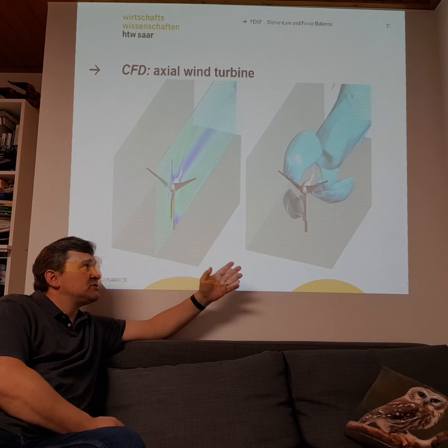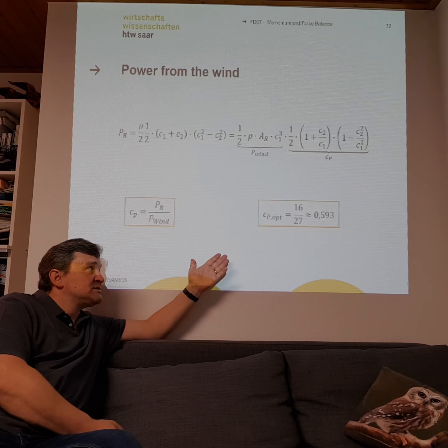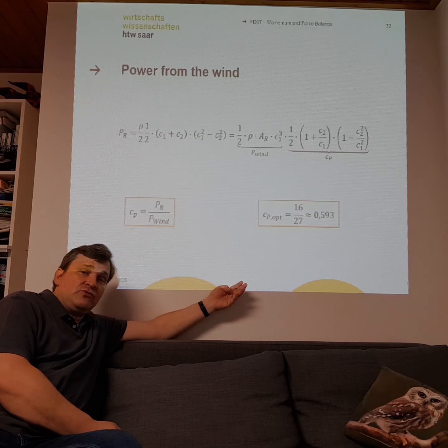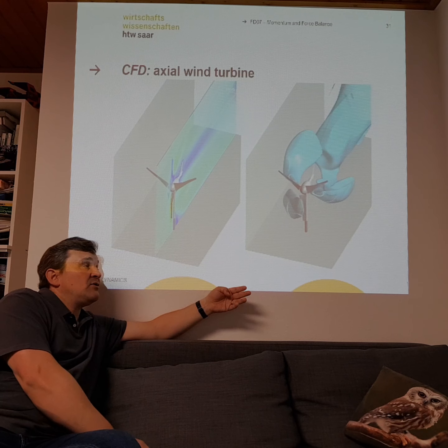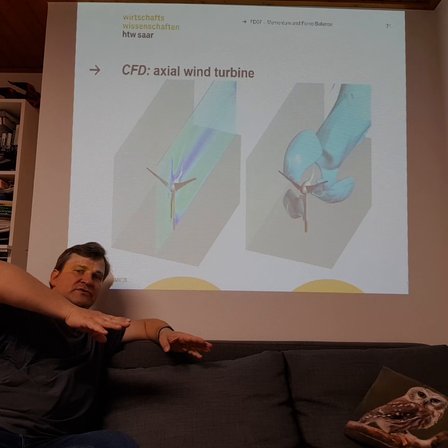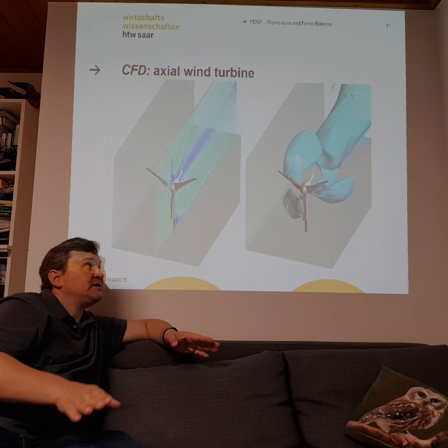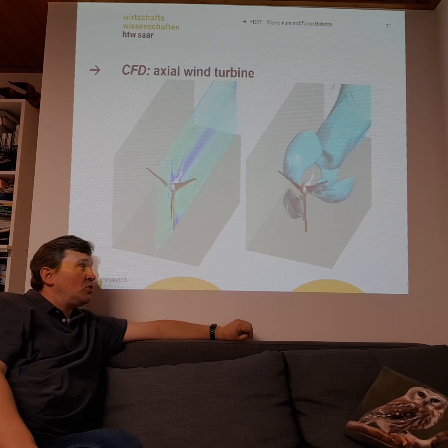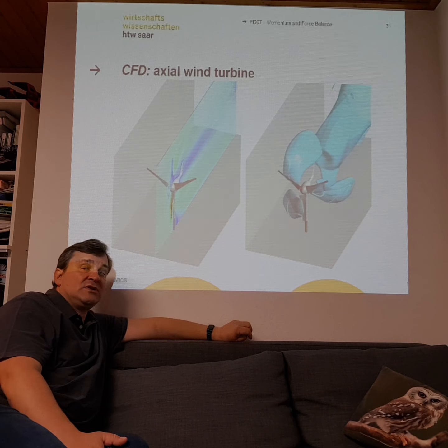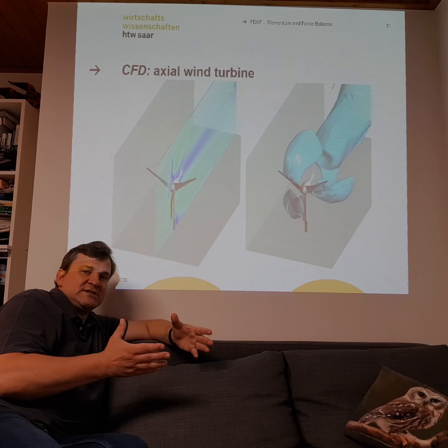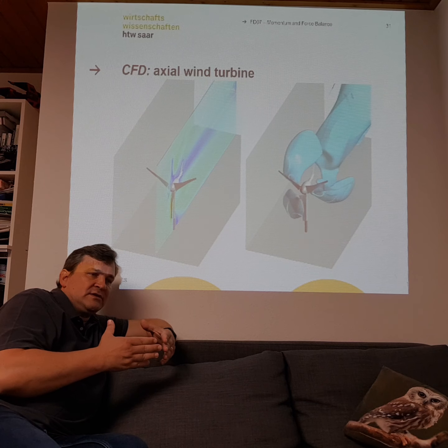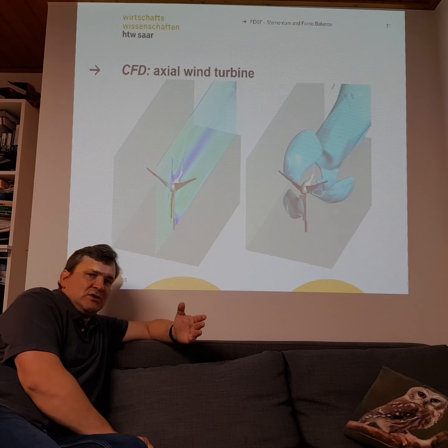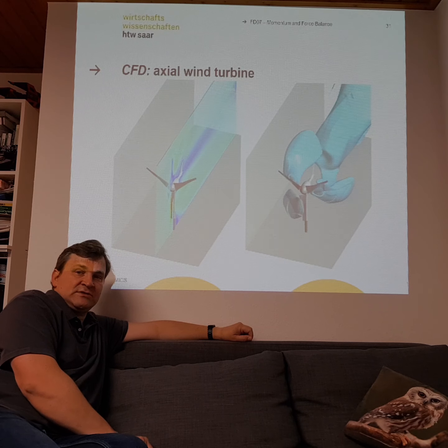Okay, sounds a bit complicated, but you can imagine this maximum efficiency will never really be true, because our spreading of the fluid will never look really ideal. It will look more like this, here we have isoplanes of velocities around the plate. You have turbulence effects, so we can nearly never reach this 100%. We will always have a bit lower efficiency than 100%.